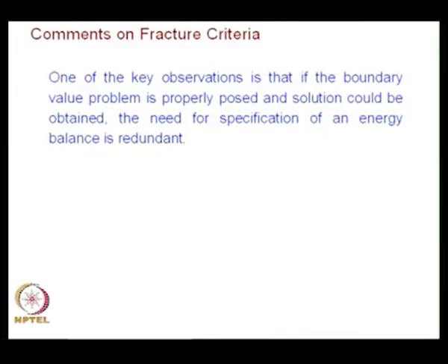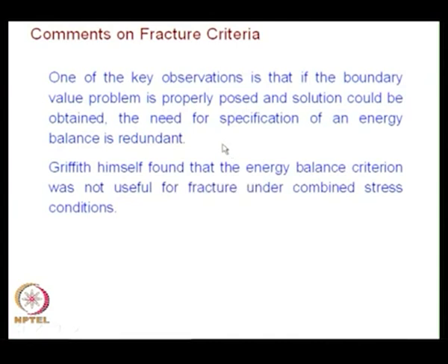And what is the consequence of this kind of a statement, that specification of energy balance is redundant? That means some aspect of the problem was not fully captured by the energy balance, and it will hit some aspect of the fracture theory. And what you find is, Griffith himself found that the energy balance criterion was not useful for fracture under combined stress conditions.